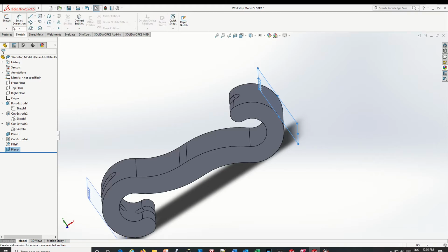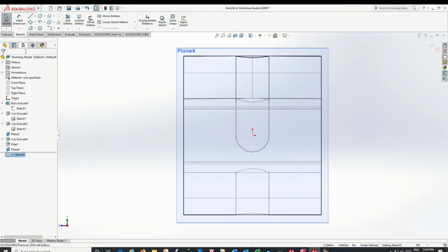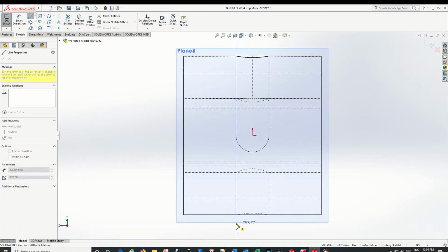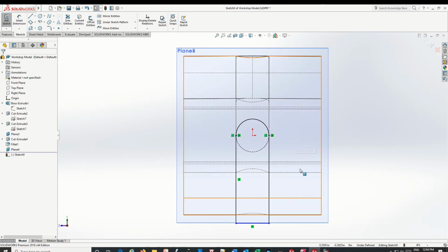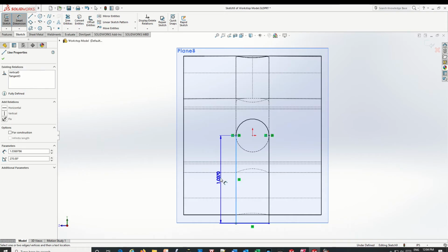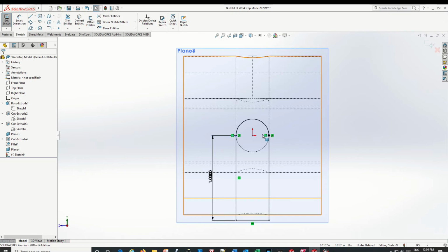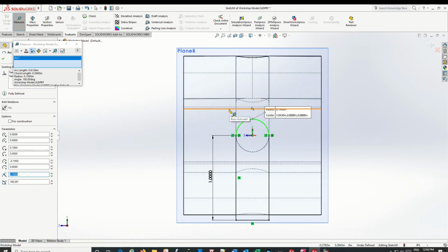So now we can sketch on that plane. Again, we can go to wireframe so we can see a little bit better what we're doing. So now this time we are cutting on the bottom. So we are going to go there, down, across. Let's see what we got here. One inch was enough. Looks like everything's good here, right? So let's have a look and make sure, measure. What is that radius? 0.195. Perfect.